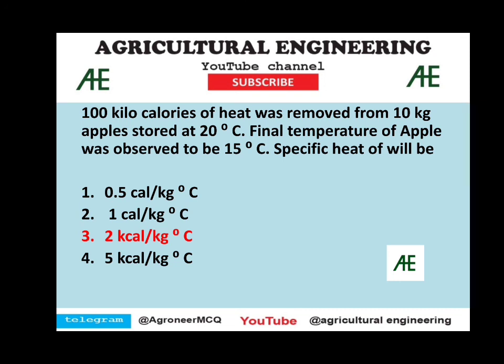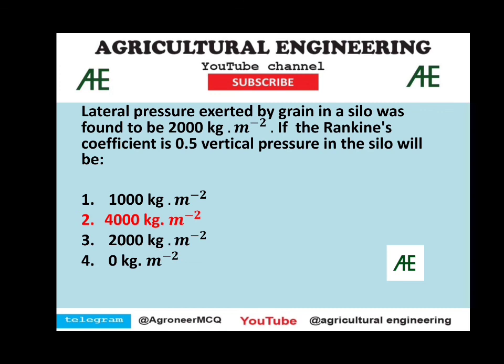So here temperature difference is 20 degrees Celsius minus 15 degrees Celsius, which is 5 degrees Celsius. And also we have given amount of heat removed, which is 100 kilocalories. So 100 kilocalories is equal to mass 10 into cp we have to find into temperature difference 20 minus 15. So we will get the answer of specific heat of apple is 2 kilocalorie per kg degree Celsius.